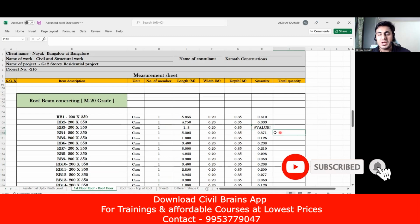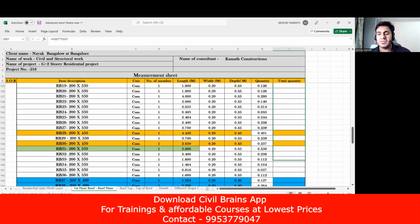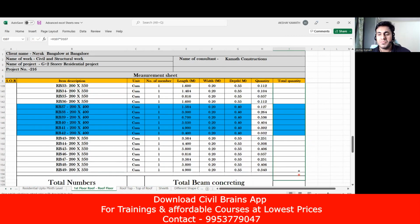Yeah, see, now again you understand why it's written hash value. The reason is, you see here, it should be 1.8, but it is double point here. You can see two dots. So I'll remove one dot. Now it will be proper. See, 0.16. Okay. So in the Excel, you should take care of certain things when you're doing that. Okay, done. And now I'll drag it. Done. Okay. All quantities have come.